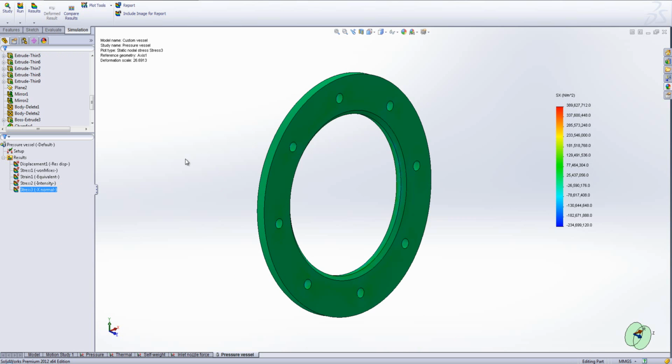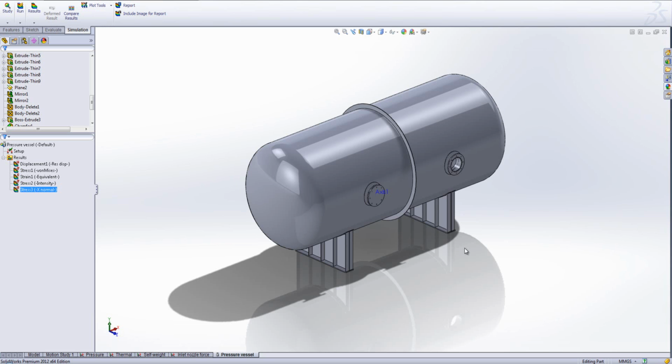Okay, let's just hide that. And finally, the ASME code doesn't specify that we need membrane and bending stress components for the flanges and covers, but we may encounter a time when there are other bulky components that will require these values. So for example, our reinforcement sections here around the nozzles might be done using solid components. We might need to calculate the bending and membrane stresses for those. Perhaps in the standards, the criteria for those are with respect to bending and membrane stresses.